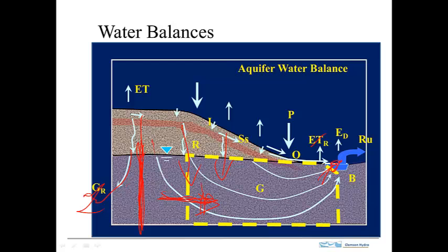Often what happens is that it's difficult to determine just where the groundwater divide is. And so you might do a volume balance that is designed to determine whether you've located the divide correctly, because then the balance would tell you whether there was groundwater flowing in or out.